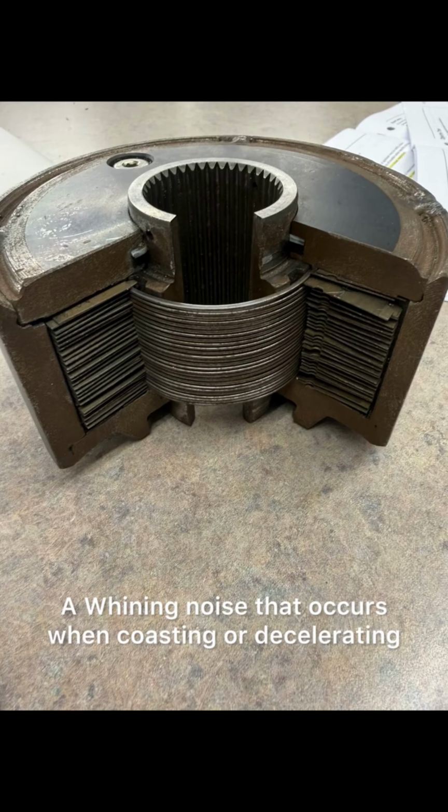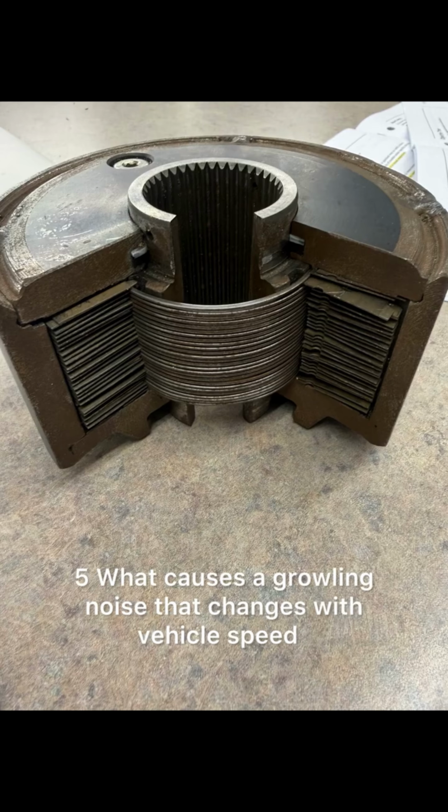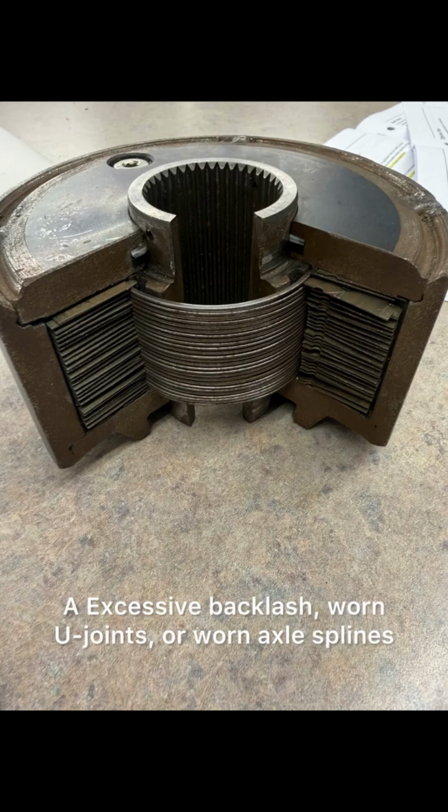4. What does constant whining at all speeds usually mean? A low or contaminated differential oil. 5. What causes a growling noise that changes with vehicle speed? A worn carrier or side bearings. 6. What causes a clunk when shifting from park to drive? A. Excessive backlash, worn U-joints, or worn axle splines.